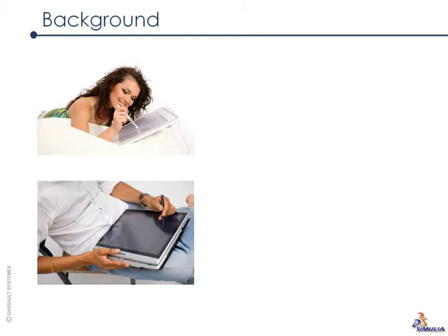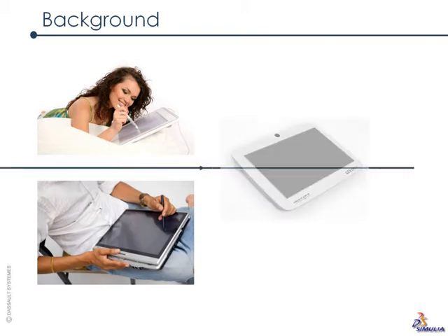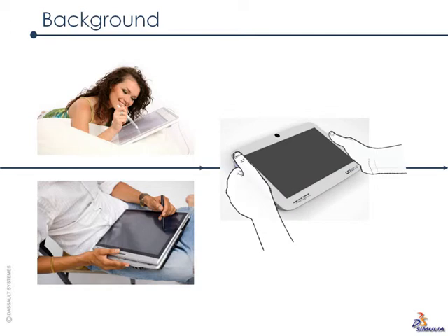A tablet PC, as seen previously, and unlike a regular laptop, is meant to be carried around and used casually. So the way I'm holding it and the way my hands are pressing on it represent specific load cases to be studied if I want the customer to be happy with the product. For example, I need to consider the feel factor of the product linked to its stiffness. A tablet PC, which is a relatively expensive object, would feel cheap to me if it was twisting too much when I do this, or bending too much between my hands when I do this.